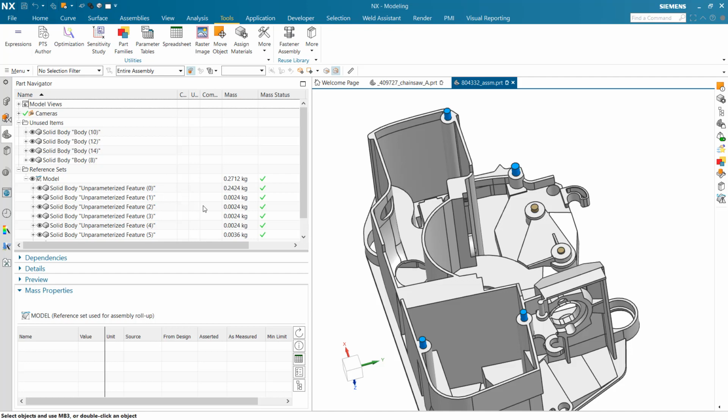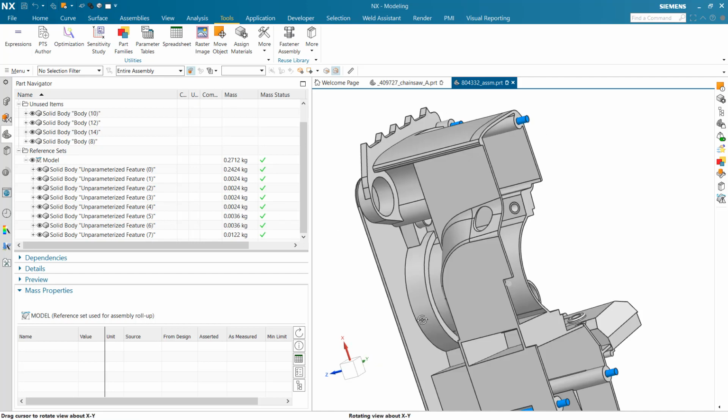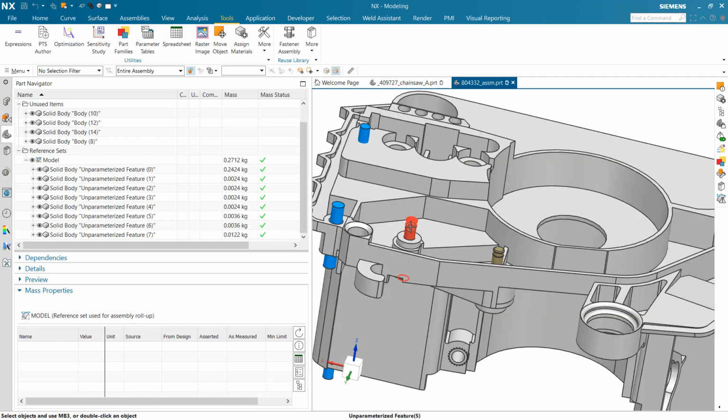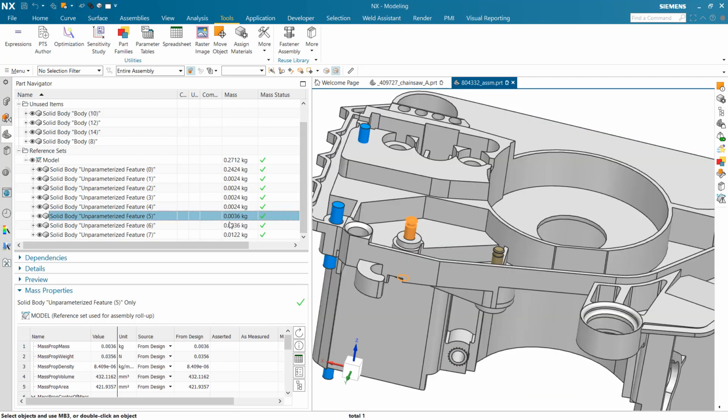Okay. So with that, we've added some properties. We've updated, made sure things are up to date. We've moved some things out that shouldn't be there. We've moved some things in that should be there, right? And that's all good. One last thing we can do here, if we really want to, or if we know more, say, for instance, if these brass inserts here, right now the geometry of those is giving us this 0.036 kilograms mass. If we know that this really should be, say, 0.004 kilograms, right? Our suppliers told us that that's an accurate number, for instance.